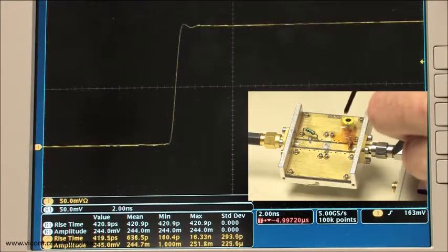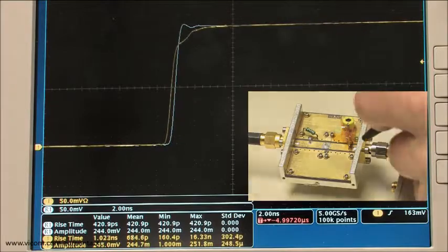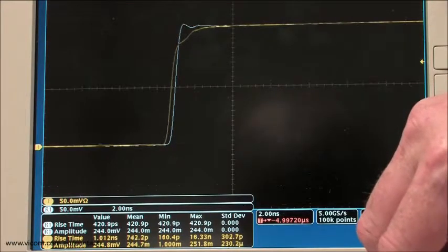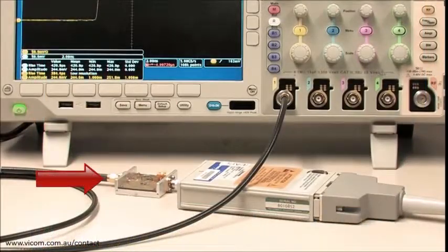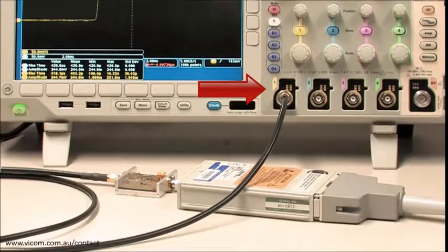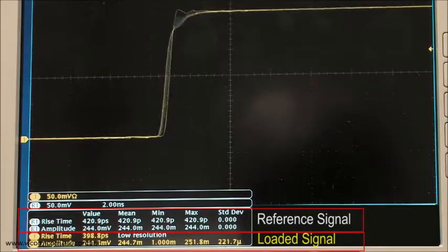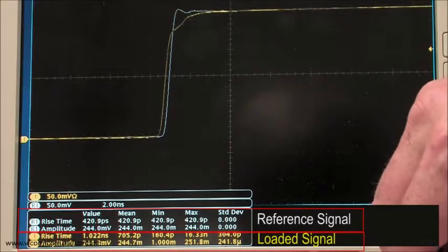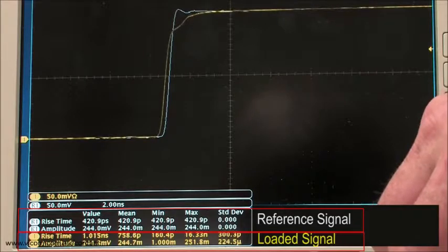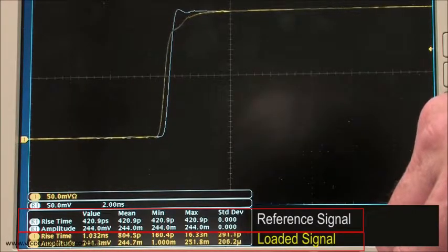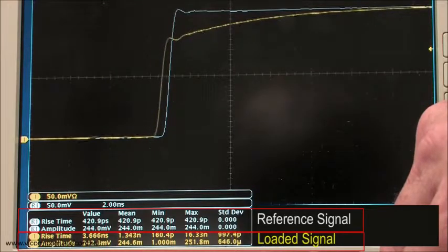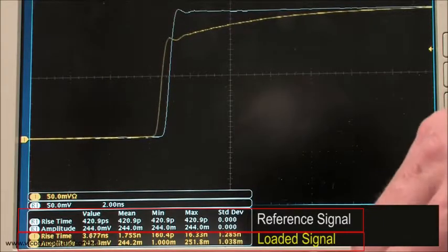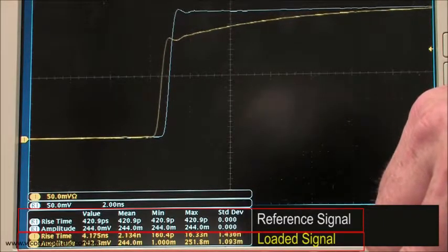We will adjust the capacitance from 7 to 50 pF to observe how probe input capacitance degrades the high-frequency content. Again, you can clearly see the DUT is directly cabled to the oscilloscope, and this is not the output of a probe. Let's now adjust the variable capacitor to see how this additional capacitance affects the front edge, so we can see how a probe with a larger input capacitance specification will do greater harm or have more loading on the signal you want to measure.